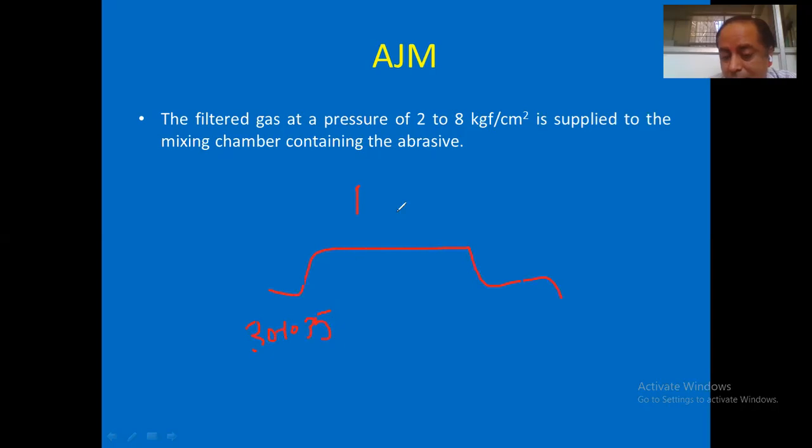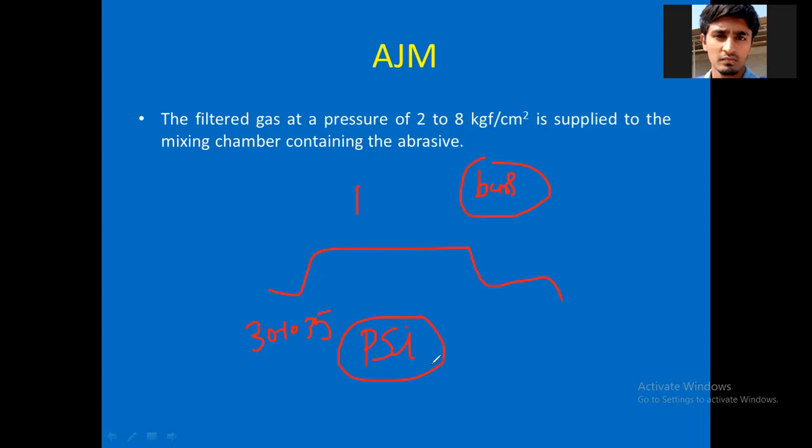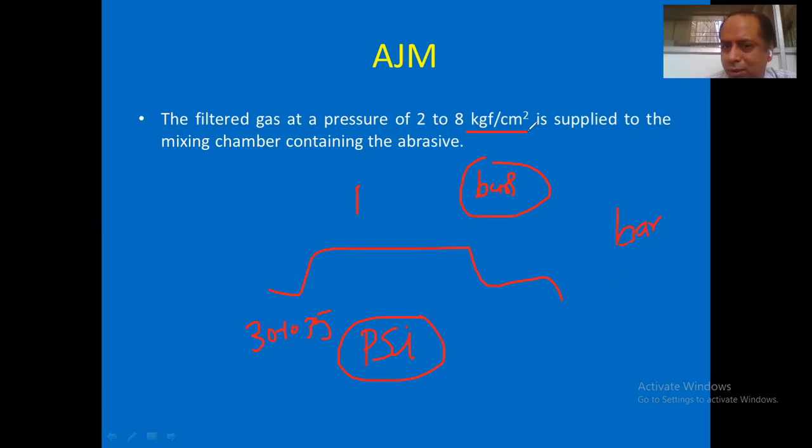बार्स में आता है क्या? नहीं बार्स तो नहीं रहता है बेसिकली। अभी नेक्स्ट टाइम जब आप जाओ तो ध्यान देना, उसके जो भी इंस्ट्रूमेंट होगा उस पर लिखा होता है it is PSI। वो जो यूनिट हम भरते हैं ना 30-35 PSI होता है। Yes, sir. तो it is पाउंड पर स्क्वायर इंच। ये ब्रिटिश यूनिट है। जैसे हम बुक में कई बार पढ़ते थे calling it a bar, 1 bar 2 bar atmospheric pressure. Here they have written this kgf per centimeter square, किलोग्राम फोर्स पर सेंटीमीटर स्क्वायर। तो ये भी एक तरह का FPS यूनिट है। Both are not SI units. SI यूनिट तो क्या है प्रेशर का, न्यूटन पर मीटर स्क्वायर। 10⁵ न्यूटन पर मीटर स्क्वायर is 1 bar। So roughly है कुछ 1.01 something होता है, but 10⁵ newton per meter square is called the 1 bar। This is the thing.